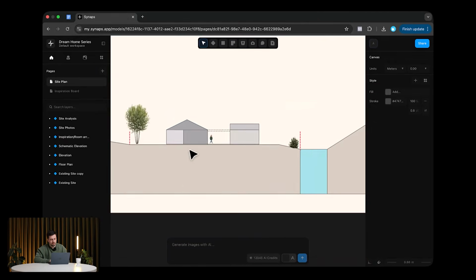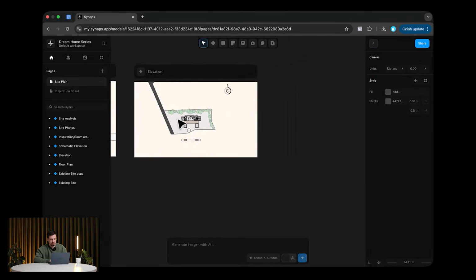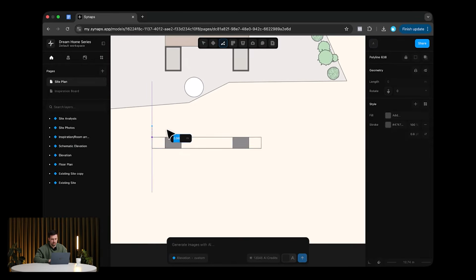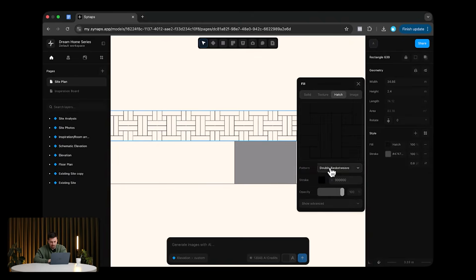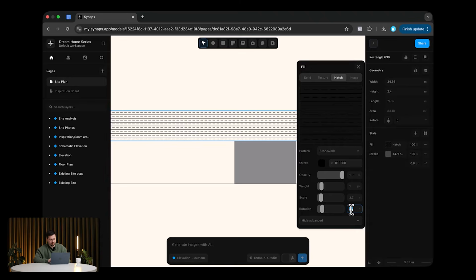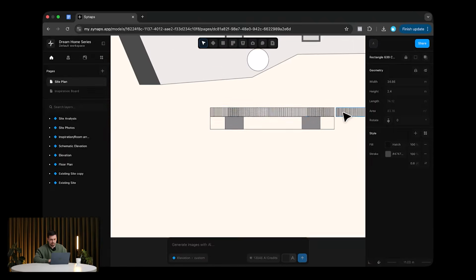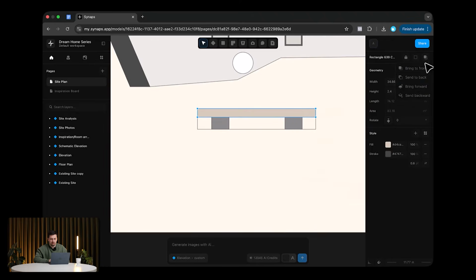This is a 25-degree angle off the roof, which I think is appropriate here. So 240 is the height from the ceiling, or where the leveling of this happens. So I'll go 0.4, I'll click enter. Let's go over on this side, and I'll close this off. In fact, I can just make this a rectangle. Let's add a hatch for these. I'll make it a lot smaller, and then I'll rotate it 135 degrees. And let's just duplicate this for now. I'll make this a solid fill of a very, very gentle light brown, and I will send this to back.